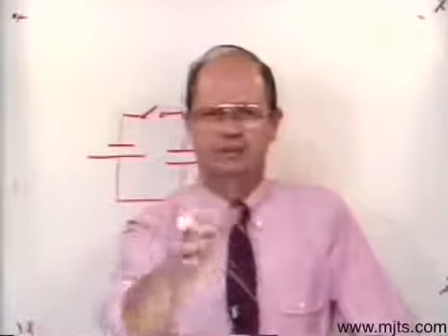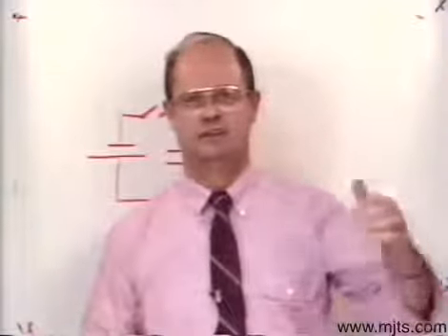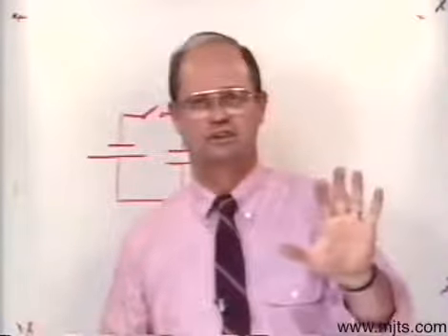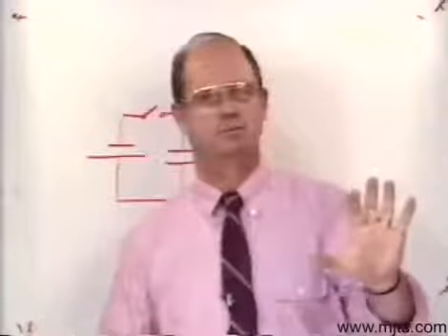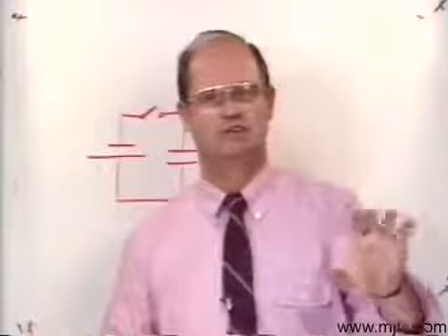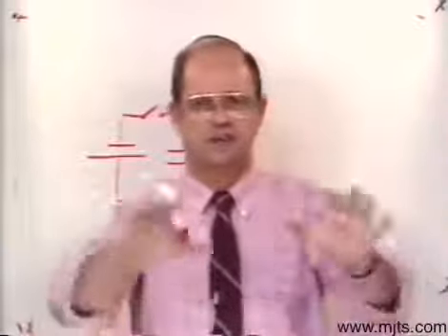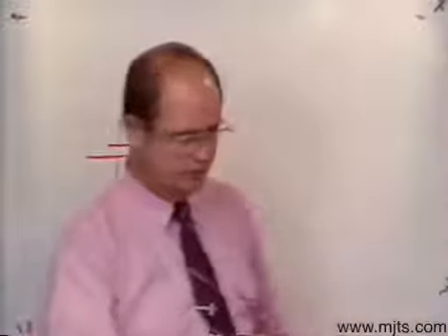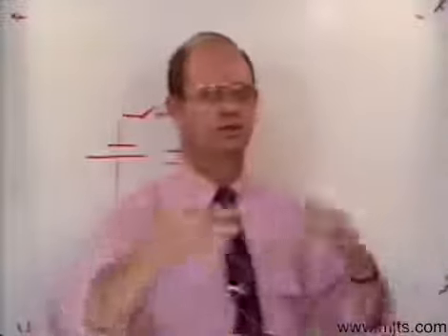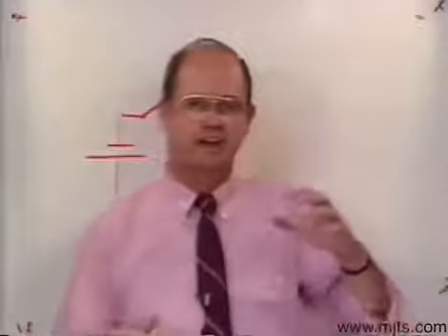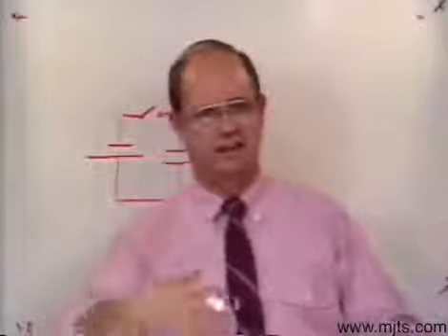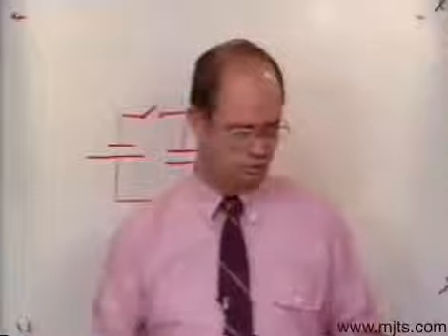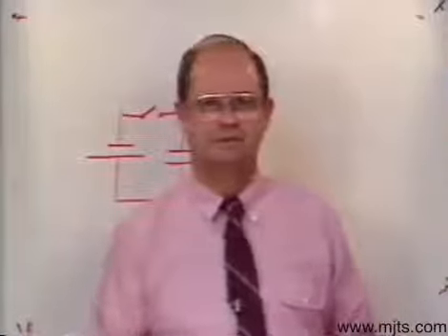So there's a completely different, opposite effect to the two. We get an opposition to a change in current flow from an inductor. We're going to get an opposition to a change in voltage from a capacitor. Just the opposite effect. And that'll be important to understand, particularly when we start applying it to our circuit. You're going to see that if I have a high inductive reactance, I can add capacitors to cancel it out, and then cut down my load in my circuit. We're going to be doing work like that. Okay?